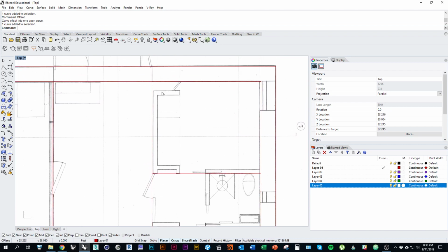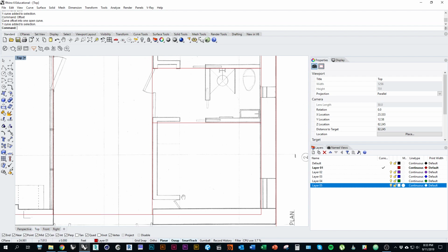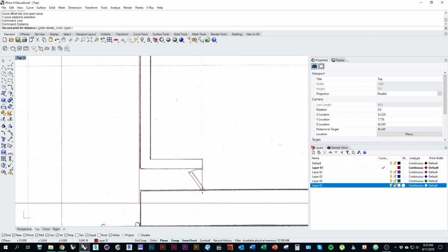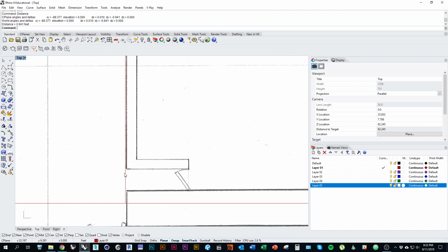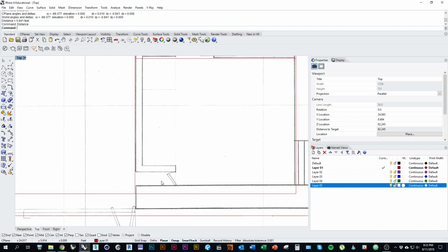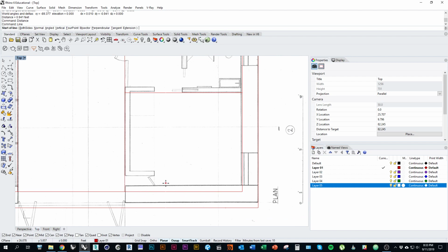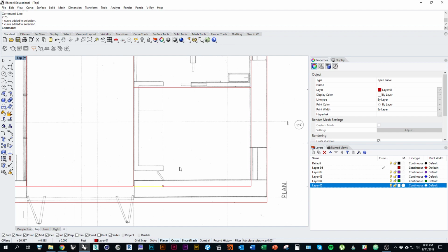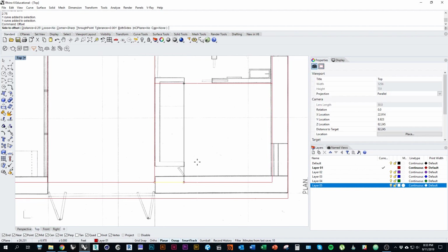first of all, I want to make this outside wall one continuous line. So I'm also going to draw a line. Let's see what, if we just measure in distance, what this gap should be roughly. So it's about 1 foot. And let's say it's about 3 feet or 2 3/4 feet deep. So I'm going to draw a line starting here, 2.75. Offset it, 1 foot.